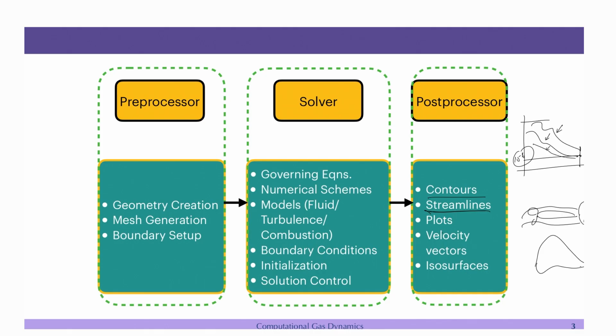Then, as I was saying, let us say you want to plot the Cp here. Cp is the pressure coefficient. You can think of it as of now pressure. It's basically a non-dimensional pressure, (P minus P infinity) by half rho u square. You will talk about what is non-dimensionalization, but as of now you can think of this as a coefficient of pressure, and let us say this is along my airfoil chord, x by C actually, let me call it. This is x and this is C.